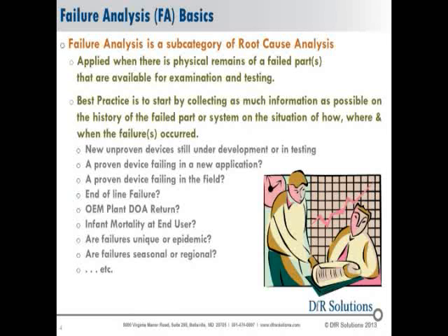Now, the best practice in failure analysis is not to start with the physical testing, but to start by collecting as much information as possible on the history of the failed parts and the situation of how, where, and when the failures occurred, or the various types of failures occurred if it's happening to a number of items in your production family.